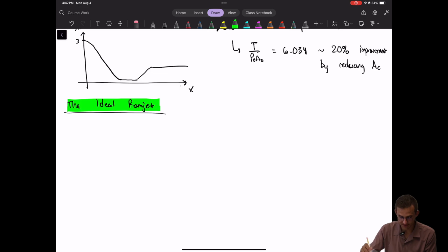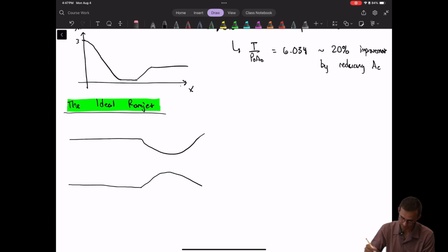Okay, and what we're going to do is convert the enthalpy that we got from the burner, now that we've increased that heat to this high value, into more speed with a diverging section of the exit. So what that looks like is you have the straight channel, and then a converging-diverging nozzle at the exit.